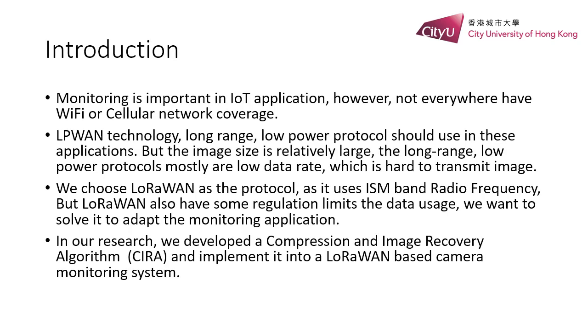We know many IoT applications require the monitoring. For example, water monitoring, smart farming, and smart agriculture. After taking photo, we need to transmit it back to the server, but not all places have good network coverage. In some rural areas or mountainside, there are no Wi-Fi and 4G signal. To transmit the data in those areas, we need to use long-range technology, such as LPWAN, Low Power Wide Area Network. For example, LoRa, Sigfox, and NB-IoT.